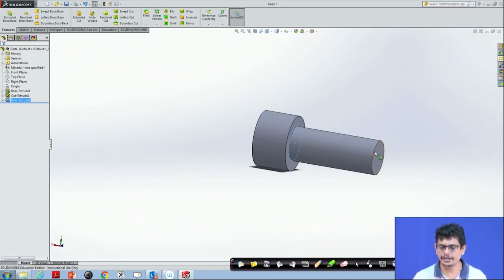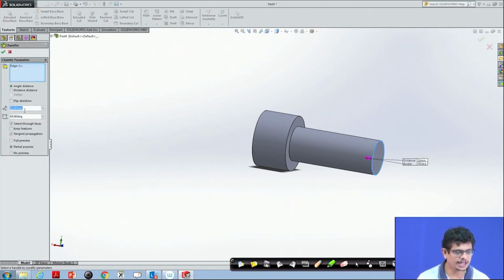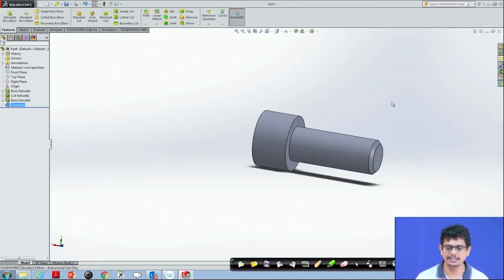Now, usually we give this the sharp corners, we avoid it by going with chamfering. This chamfering we can go with 1 mm with 45 degrees, so that the stud is done. So, once this bolt is done, what we can do is we make a helical path around this and a triangular kind of cut with a nice curvature and pass with match with this pitch and height thing and make a thread out of it.